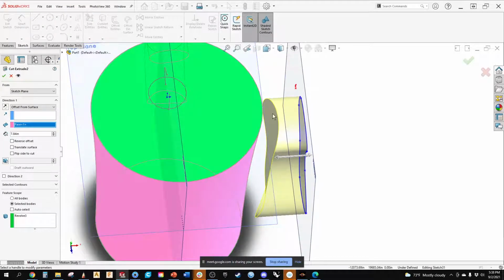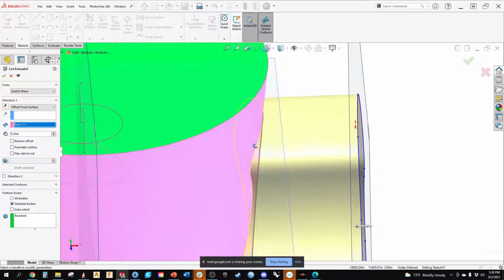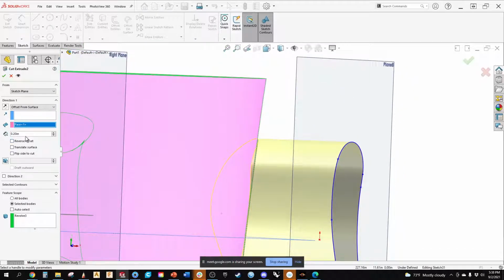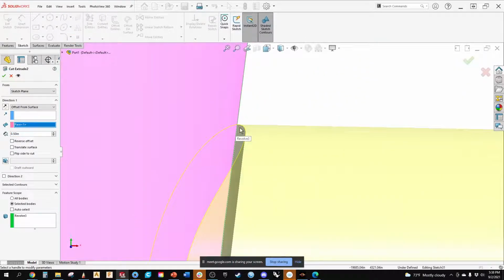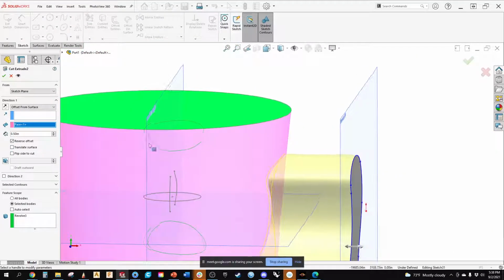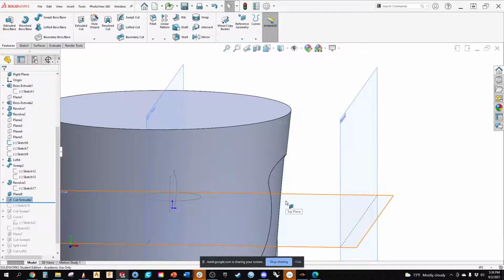You can already see that that shape is following that contour. I'm going to say I want it to be offset by 0.2. Now, you know what, let's go with 0.5. You can see how it's not actually touching that face. It's cutting off the different direction, so I want to reverse the offset so it goes inboard. We'll hit select. And what it does is it recognizes that surface and creates that contour.